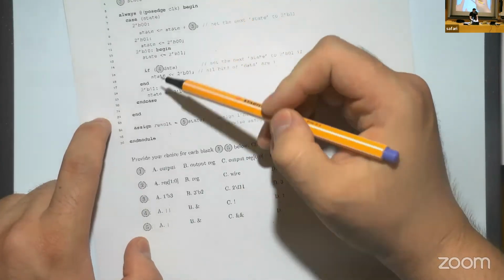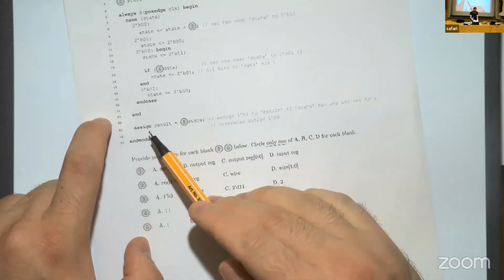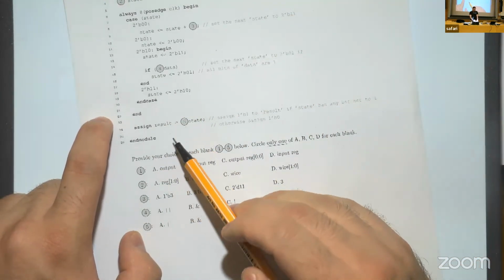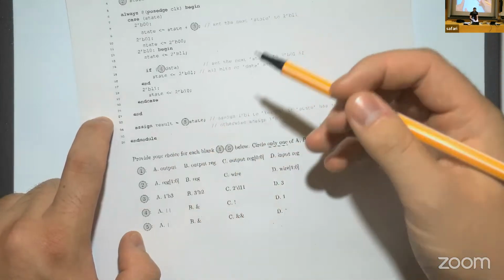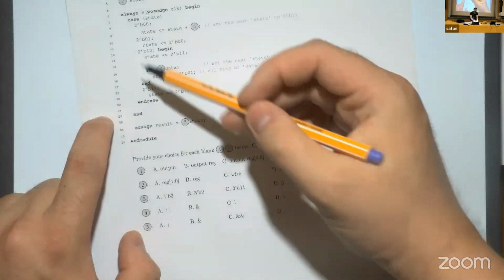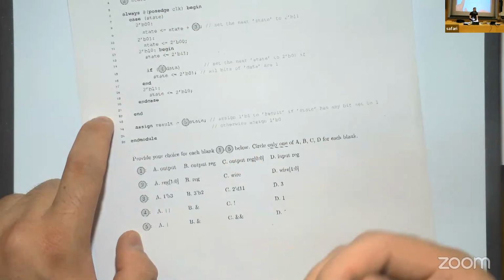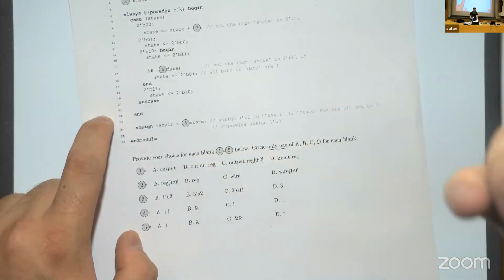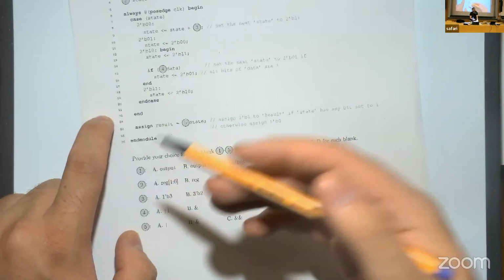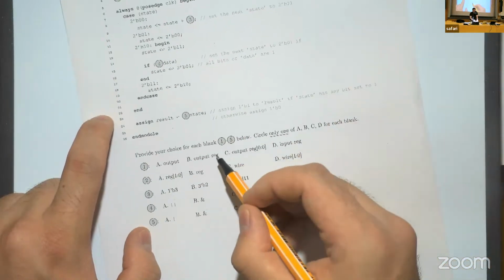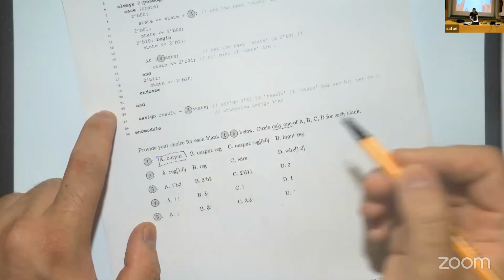When we check line 24, we see that they used assign. If it was reg, we couldn't use assign here, because a reg can only be updated inside the always block, and we cannot use the assign keyword for this one. We should use a wire. So which means that result is a wire, and we won't use reg over here and here. So which makes A the correct option.